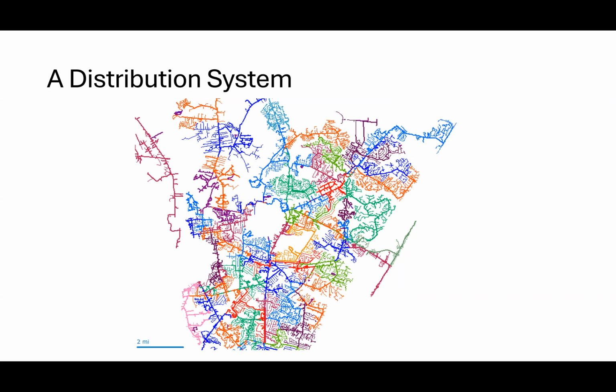Okay. So usually there's 2 types of transformers in these systems. Usually, there's the overhead cans. So when you see like a grayish can on a pole, right? You look up and you see a can hanging up there. That's a transformer that's taking the voltage down from 13 kV or 24 kV down to just, let's say, 240 volts. Or what you see is a pad mount transformer, which are those green boxes that are on the ground. All right. And which one you have depends on whether it's an overhead system or an underground system.